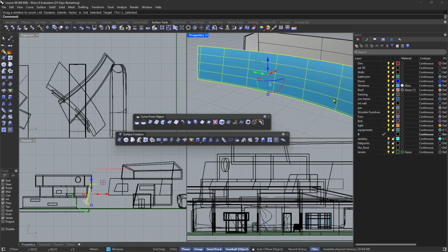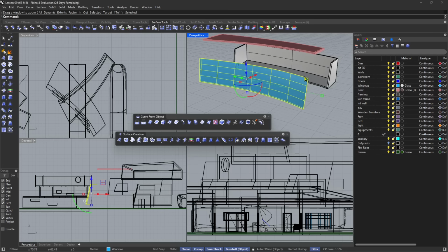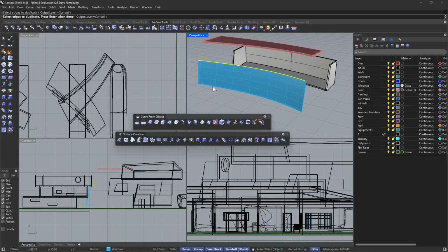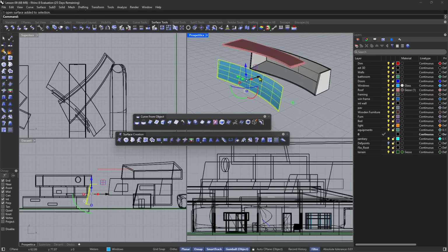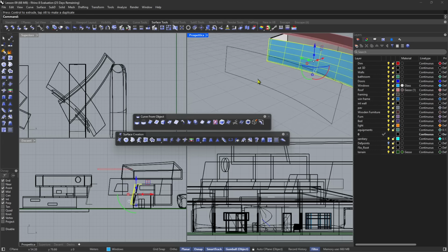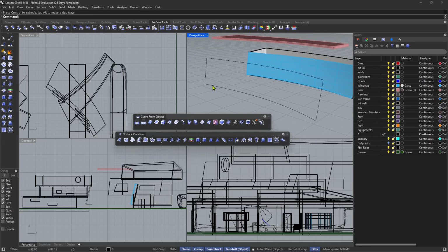We can extract the curves or just use the edges and create something else. So with the curve from edge object, we can duplicate an edge. So I can do, for example, one rail sweep with this, or two rail sweep. I can do a loft. I can do a lot of things. So let me extract these curves from here just to show you different ways we can do things if they don't come out exactly how we want. So let's go here through the surface creation.